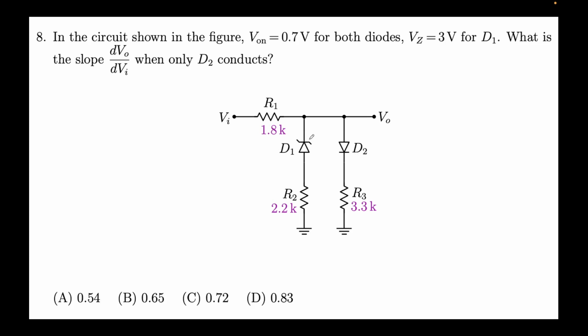Before we go on to this problem, this is the symbol of a diode that we typically know, a PN diode, right? As I told you, this is P semiconductor, this is N semiconductor, and this is the typical symbol of this diode. And as I told you, the IV characteristics, ID versus VD, if I draw the real world looks something like this, and at some point of time it just breaks down. So this is what we know as V breakdown, the breakdown voltage of a diode.